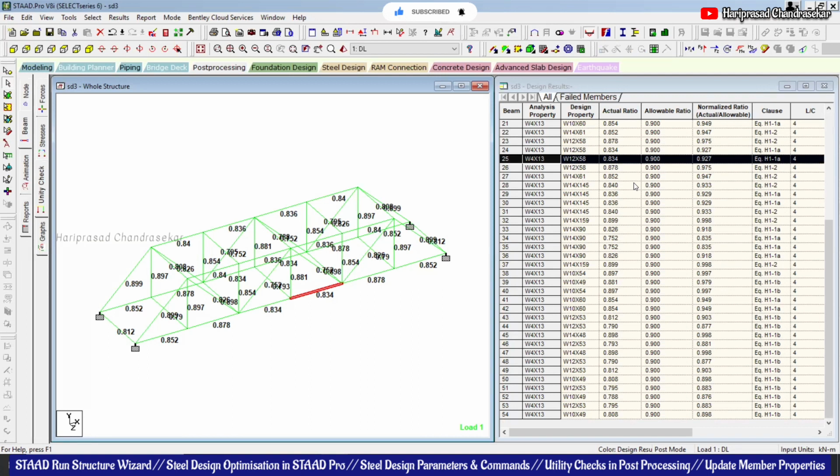There might be some formulas provided. So the ratio in the sense it will try to calculate the load with the self weight. It should not be more than 0.9, so anything below that is getting passed. That's why everywhere we are getting green color, and you can see the values less than 0.9. Okay, you got the right point.